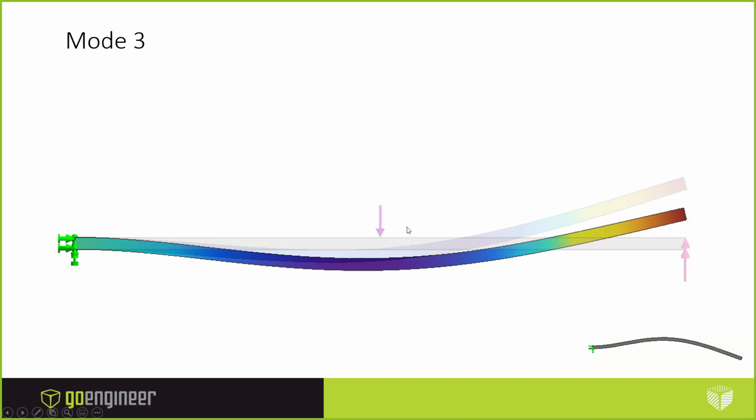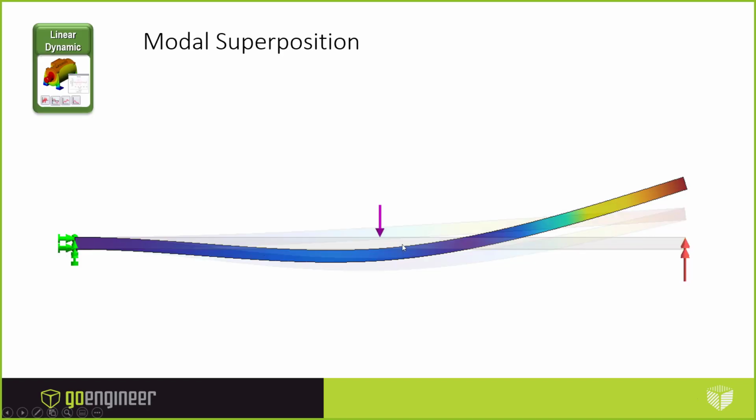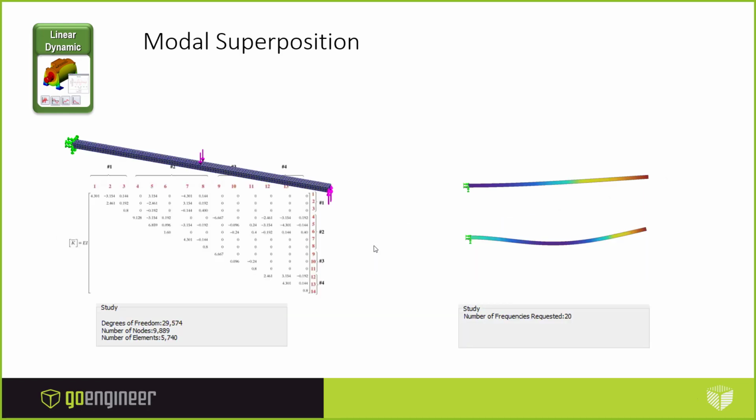If I add together +1 thickness to -2 of the thickness, I get about -1 of the thickness. So you can see that this arbitrary static deformation is really just a combination of modes, a combination of just adding together those sorts of vibrations. And any deformation can potentially be looked at that way.